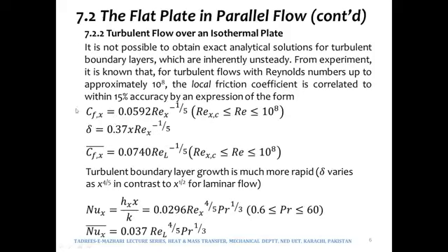And CFX, the local coefficient of friction if the flow is entirely turbulent over the isothermal plate, is given as 0.0592 Reynolds number to the power minus 1/5, and CFX bar, the averaged friction coefficient, is given as 0.074 Reynolds number raised to the power minus 1/5.